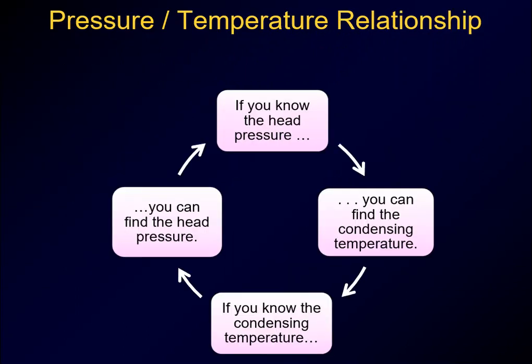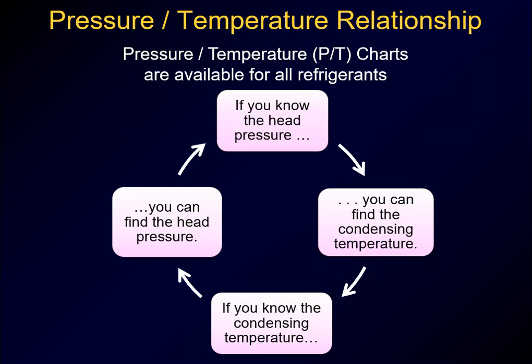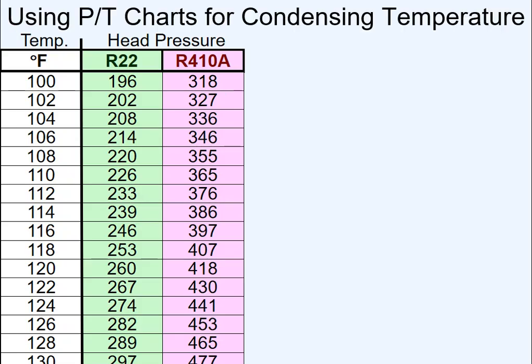And I will hand you out, like I said, a full-blown PT chart, but this actually has a small example of one. If you know the head pressure, you can find the condensing temperature. If you know the condensing temperature, you can find the head pressure. So here's an example of one. This is kind of like what I'll be handing you.